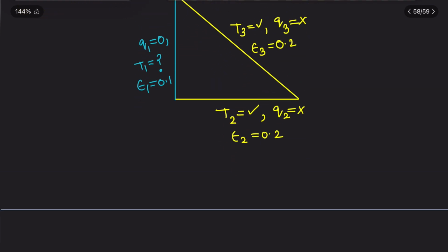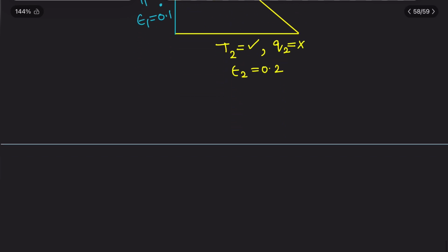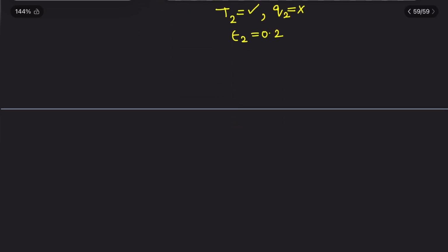So this is again an enclosure containing 3 surfaces. Now what is the first step? You can start with any surface, so let me start with surface 2. For any surface you need to first write the EB, EB2. Then you need to establish the connection to J2, the radiosity.